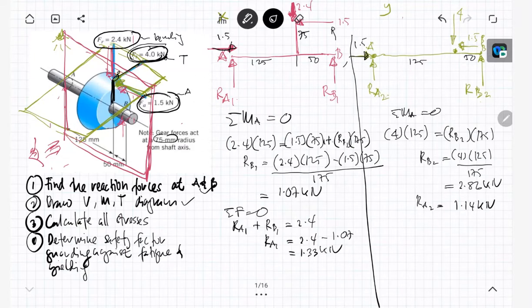But for the radial force causing bending, it has the frequency. It has the alternating stress. For the tangential force causing the torsion, where the shaft is twisting, there is no alternating shear stress here, same as the axial loads. So there's no alternating stress.